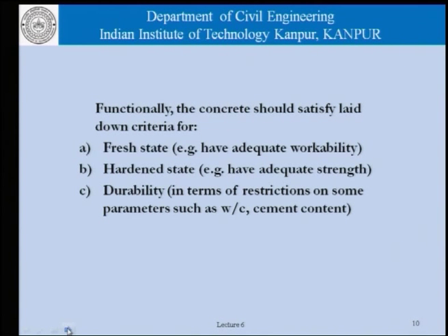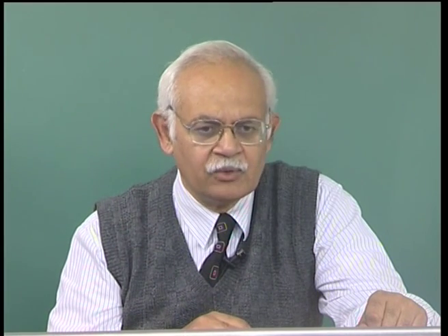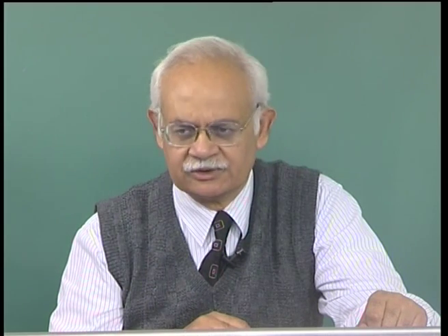For example, there may be restrictions on parameters such as the water cement ratio, the cement content and so on, and there may be some requirements in terms of temperature rise during setting and so on and so forth. So, basically the properties of concrete that we study have to be around these functional requirements that a concrete needs to satisfy.